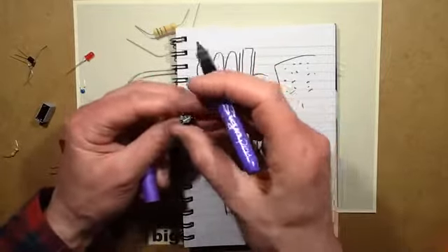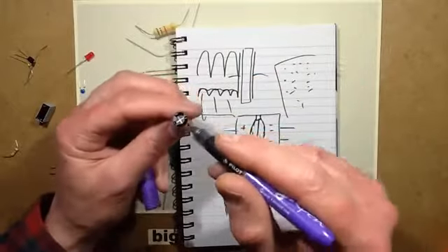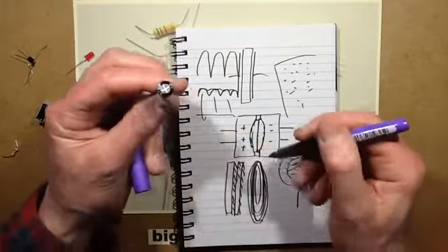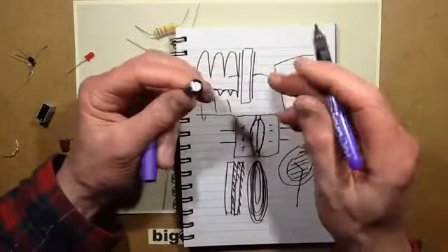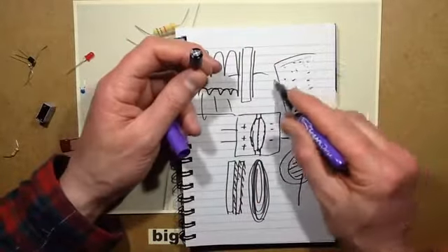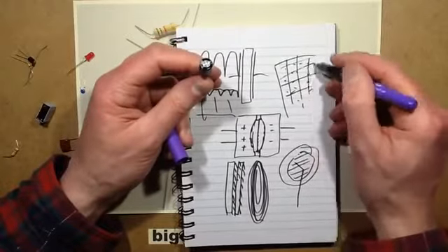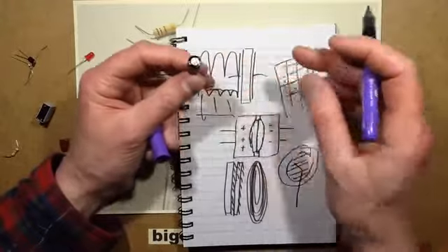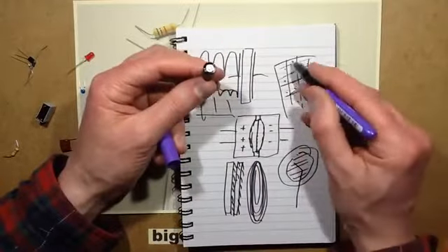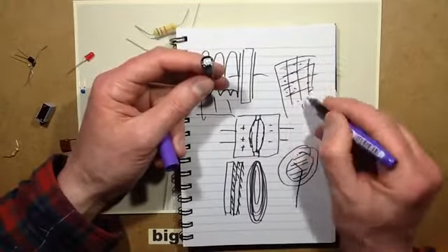They're put under a lot more stress. And if you look at the top of this one, you'll see there's a little cross on it, and that's a safety vent, because when these fail, what actually happens is that oxide coating can be perforated, and that's really common if you accidentally connect them in reverse, because it relies on the polarity to keep that oxide coating intact.